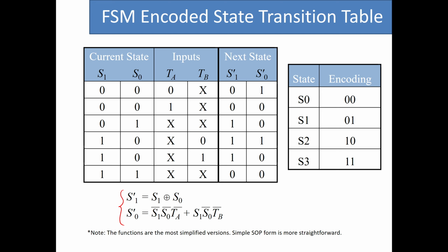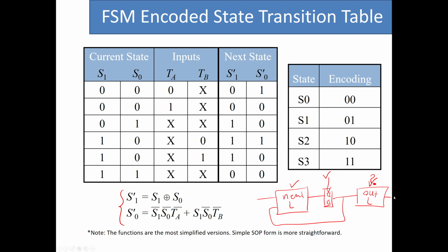So now you might say, okay, we are kind of halfway through the procedure. So in the Moore FSM, we had this thing. This one was the output logic. This one is the next state logic, right? So we found out about this. We also found out about this one as well, right? Because based on the encoding, we realized that we need to have 2 D flip-flops inside this register. So what is left is basically this output logic.